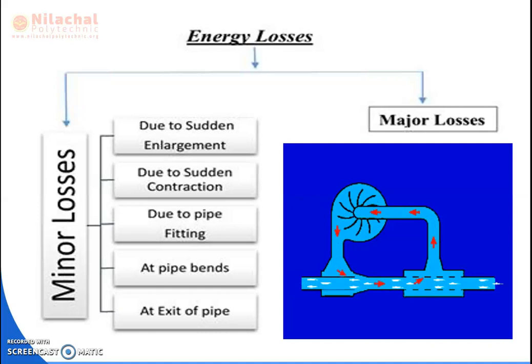As the pipe is fixed and the liquid is moving at velocity, the sliding contact between the two surfaces causes a force, and that force resists the motion of the liquid while the flow takes place through the pipe. The major loss in the pipe is due to friction.